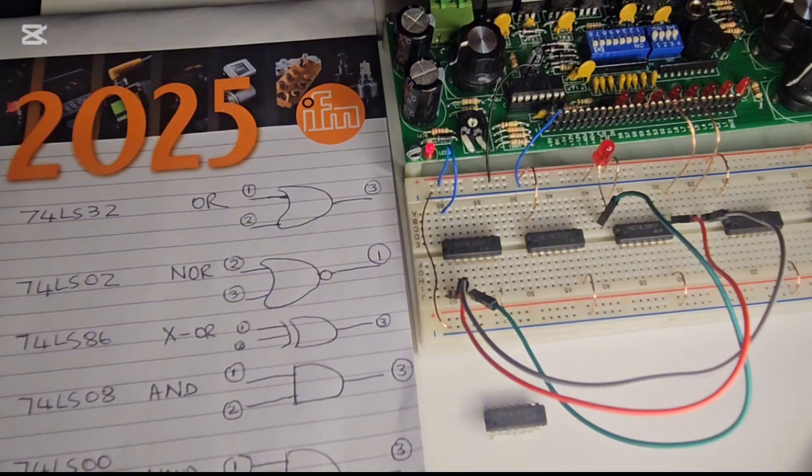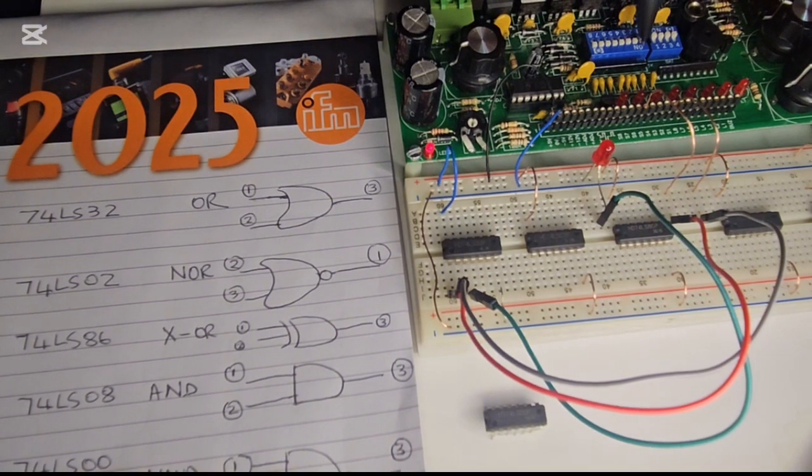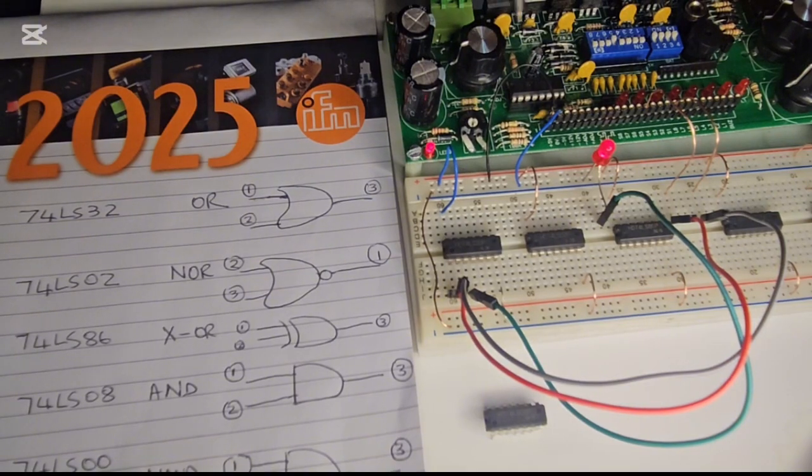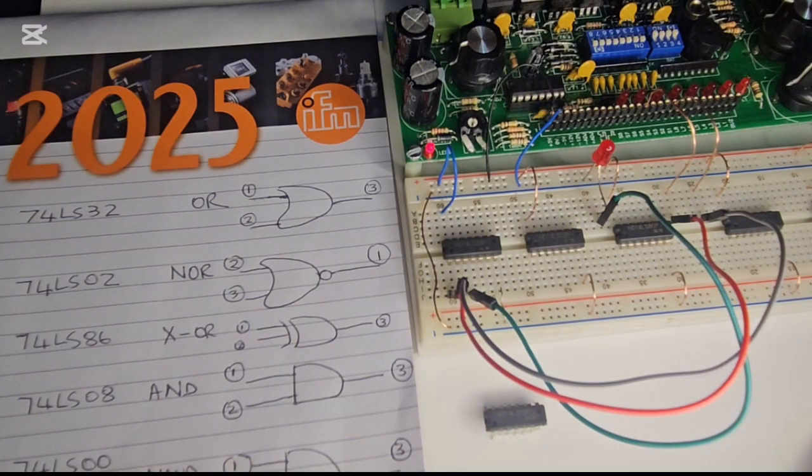Now let me make just input 1 on. Input 1 is on, back off. Okay. If I make input 5 on, input 5 on. So when 1 or 5 is true, my output comes through. If both of them are true, my LED stays on. But when both of them are off, then my LED goes off. So that proves that the OR gate is doing exactly what it's supposed to do.